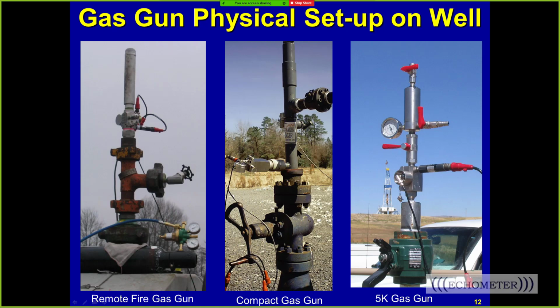We're shooting through the tubing, and we use a compact gas gun because we can do an explosive shot. Low pressure has a somewhat larger volume chamber, so we typically like this gun because if we track a plunger, we can cock it and keep the liquid from coming into the gun body when it unloads liquid to the surface.